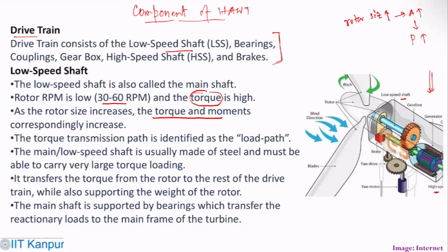So one has to have some kind of trade-off between the power output that one would like to have for given conditions, given location or given wind speed, and how much rotor diameter could be affordable. This is where system level optimization, integration, and optimization become important, because within the constraints, one has to see how much power can be maximized. This is one of the things that one has to look at.